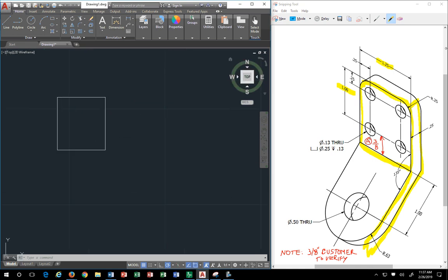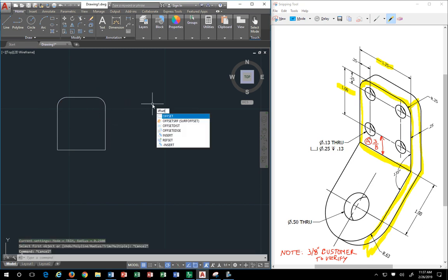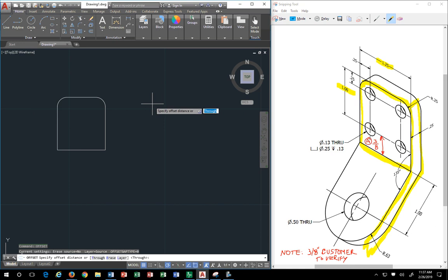We have this, so then we do what? The fillet command, remember that? The radius, that's already been covered in class. So the radius is 0.25. That's how you get the corners. Okay, then we have our shapes, and what did I always suggest? What's the most popular command that you'll find yourself using is offset 0.25.